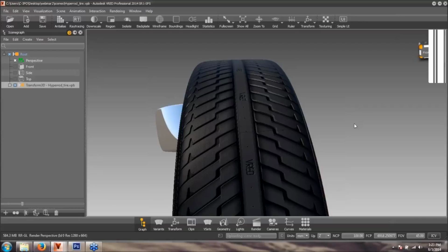When you hit the home button, that sets your view to the one that you set, which is not quite the same as animating a keyframe, which we'll get into in just a bit. Also, depending on what object is selected, you can quickly jump to different viewpoints with this navigation cube. These are not truly orthographic views.